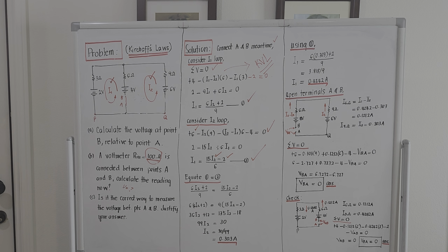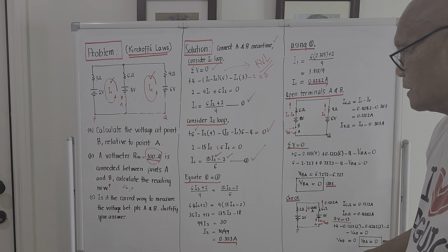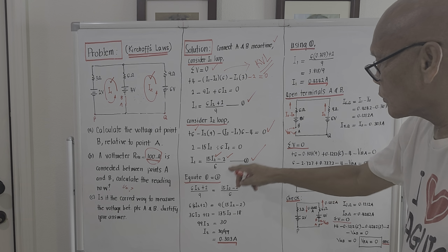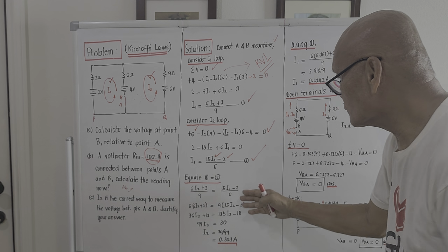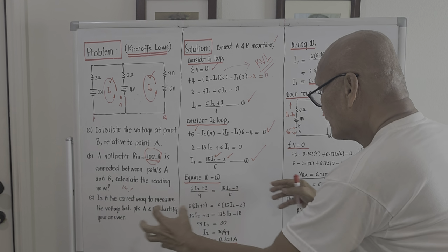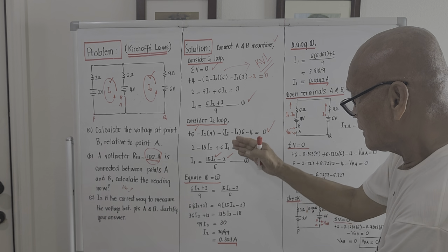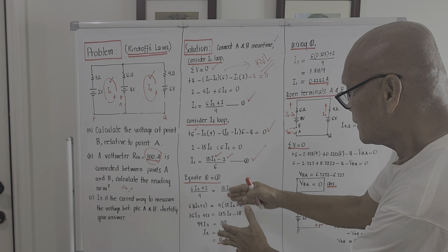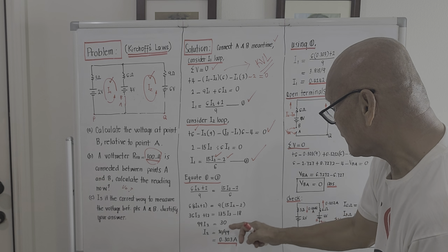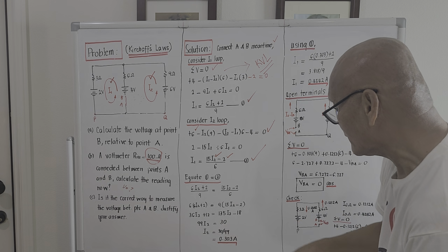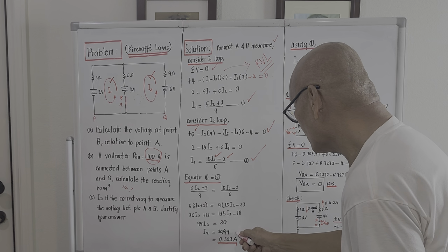So this is now two equations and two unknowns involving I1 and I sub 2. We equate equation number 1 and number 2. So equation 1, this is equation 2. If we try to simplify this one, I won't go through each step, I will just give you the answer now. I sub 2 will be the ratio 30/99, and this is 0.303 amperes.